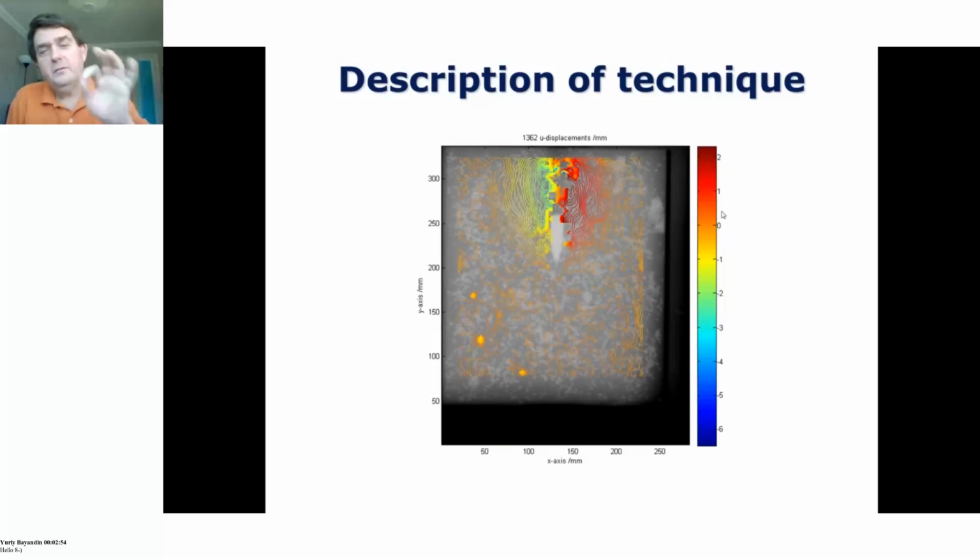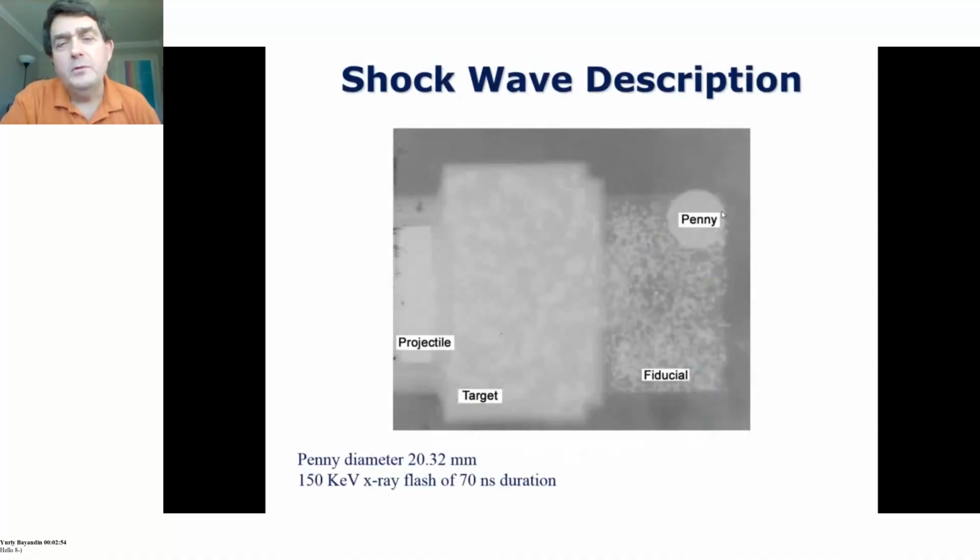Okay, so there's a physical projectile going into the sand, causing it to move, causing those lead filings to move. Those lead filings are forming a background image. We're not tracking individual lead particles, we're tracking the image produced by those particles together. So it's a pattern correlation, not a point correlation technique. And you can use it to look at shock waves and wave motion through relatively complex material.